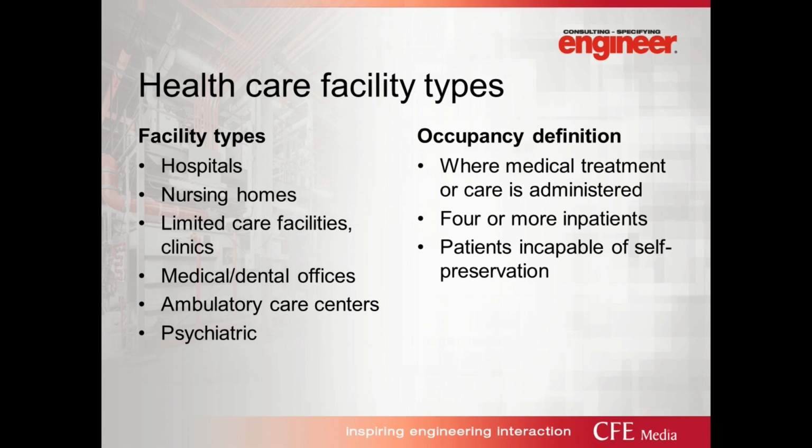A healthcare occupancy is specifically where medical or other treatment is simultaneously administered to 4 or more patients on an inpatient basis. This is where the patients are mostly incapable of self-preservation due to age, physical, or mental disability. So there's an important distinction between a facility and an occupancy that cannot really be interchanged. All healthcare occupancies are considered healthcare facilities. However, not all healthcare facilities are considered healthcare occupancies.